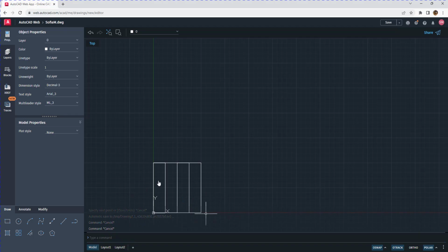And now I don't have to do continuous lines. I'm just going to pick another line, and I'm going to draw my horizontal ones. So I start in this same corner. I go down by 25 units. Then I go to the side. Then I go down again 25 units, and I am at 50, which is right in the middle. I go down again 25 units and to the side. And hit escape if you don't want to draw any more lines. Okay, so this square right here is just for one letter.